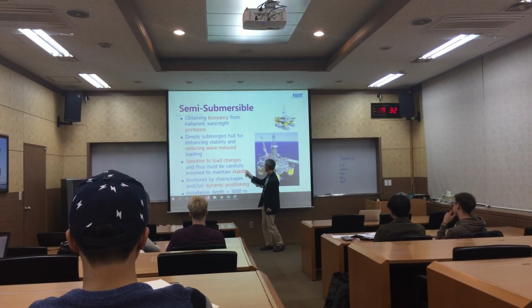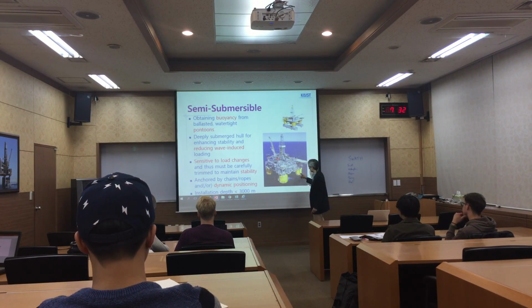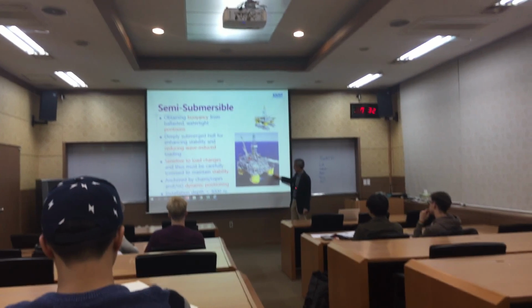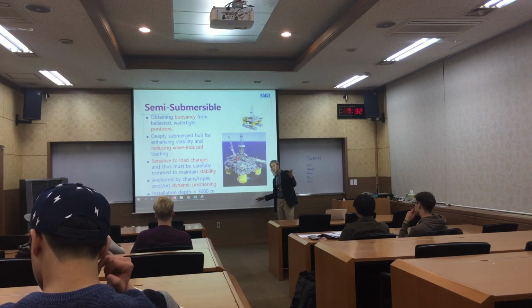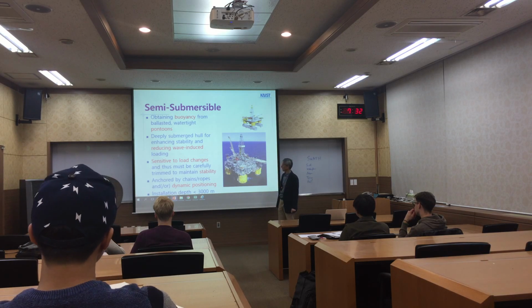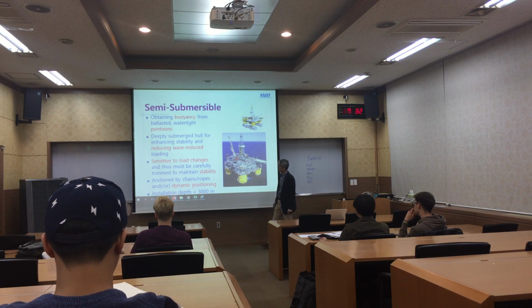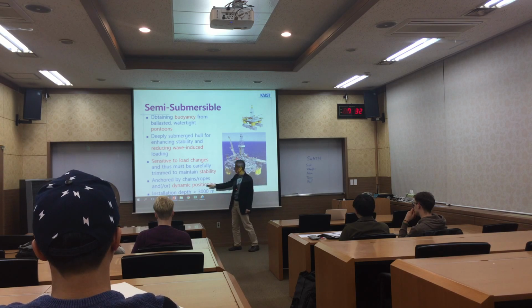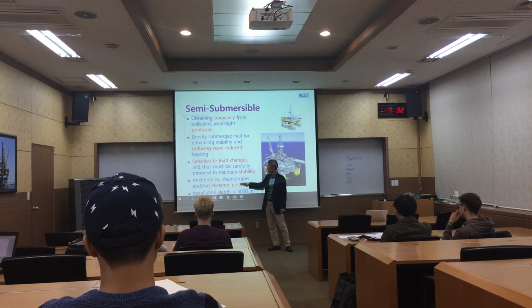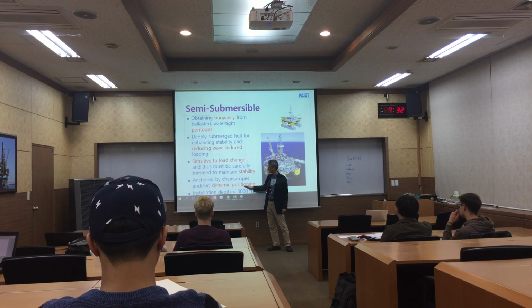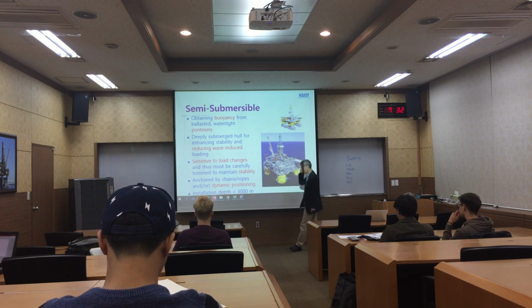When something happens, say some cracks occur so that water comes in, it can be trimmed, but stability can be lost. Anchored by chains and ropes, so you need to have dynamic positioning. Every floating type in high depths needs a dynamic positioning system.